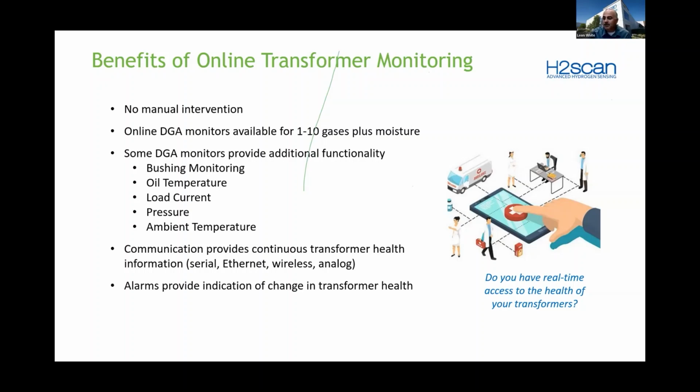There is a trend in the industry to go to higher bandwidth and easier ways to connect, like Ethernet, wireless, but analog is still around, 4 to 20 milliamp and so forth. That stuff is still around. Protocols like IEC 61850 require Ethernet, and so getting data from devices that don't have an Ethernet port, you have to run that data into serial converters that convert that to Ethernet, a gateway of some sort.